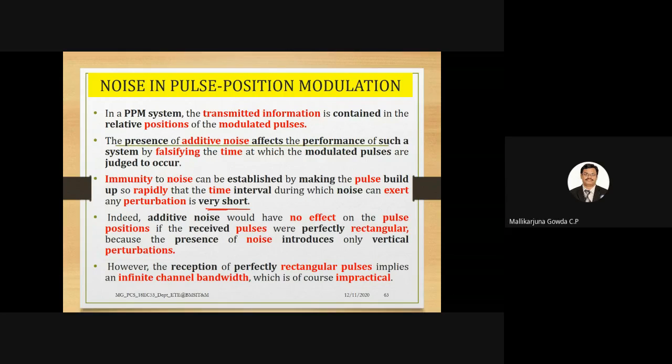This means the additive noise would have no effect on the pulse positions if the received pulses were perfectly rectangular, because the presence of noise introduces only vertical perturbations. I hope you understand my point; I am discussing this to understand the noise in PPM.